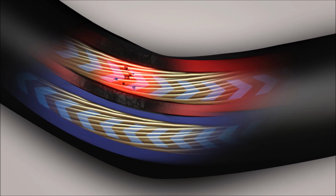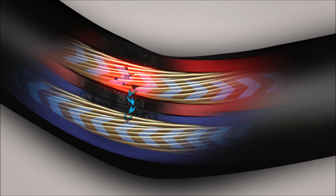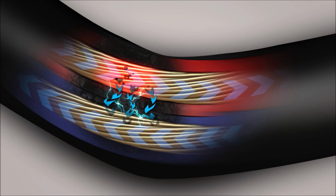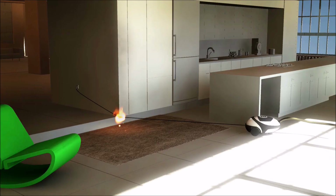This phenomenon cannot be detected by a circuit breaker or earth leakage protection system. To flow through the burned insulation, the current produces electric arcs, which in turn burn more insulation. This is how hotspots start a chain reaction that can cause a fire. Even a tiny leakage current can start a fire that can spread through the rest of the insulation and onto anything else that may be nearby.